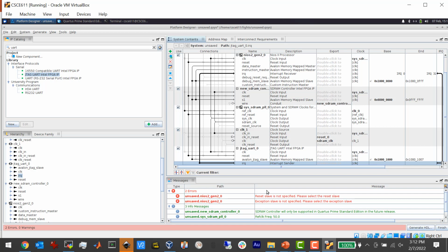So I would have to create a custom device tree if I wanted to boot Linux on here, in other words. Because I have the ability to change those addresses, and if I change the address in hardware, it needs to be updated in the operating system, or in this case, in the HAL.